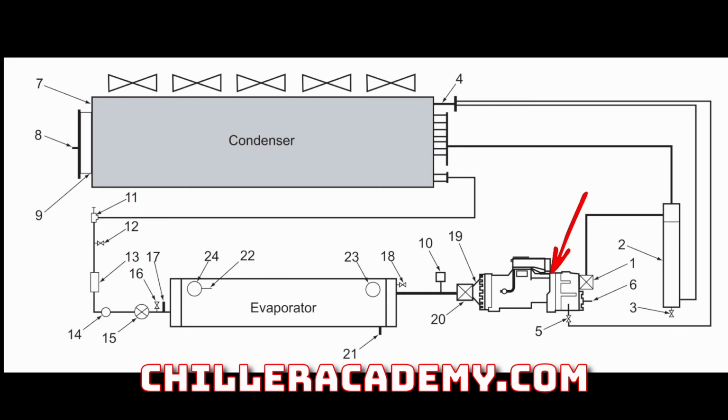You're still feeding 60 hertz from the grid to it, but because the manufacturer has complete control of the motor and the drive package, they're putting in the 200 hertz output, and having that extra hertz gives much more refinement in speed control. But also, from what I understand at least, the higher hertz allows better efficiency with the load and the torque on the motor.